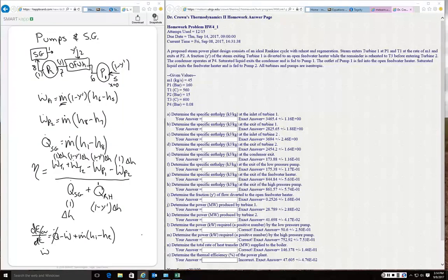It's adiabatic, or Q is 0, Q dot is 0. Then when I bring the work to the left side of the equation, it would equal m dot times H inlet minus H exit.